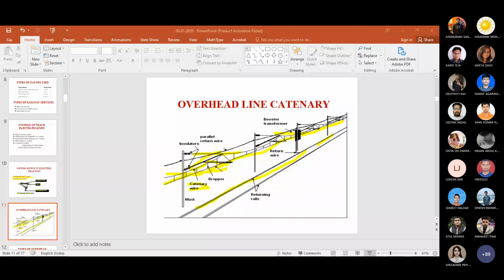When the current value is high, you keep the full resistance, then gradually you cut the resistance value. Why do you do it this way? Basically, everything happens when the back EMF is zero. After some rotations, the back EMF gradually develops, an induced EMF. Why is that induced EMF known as back EMF?